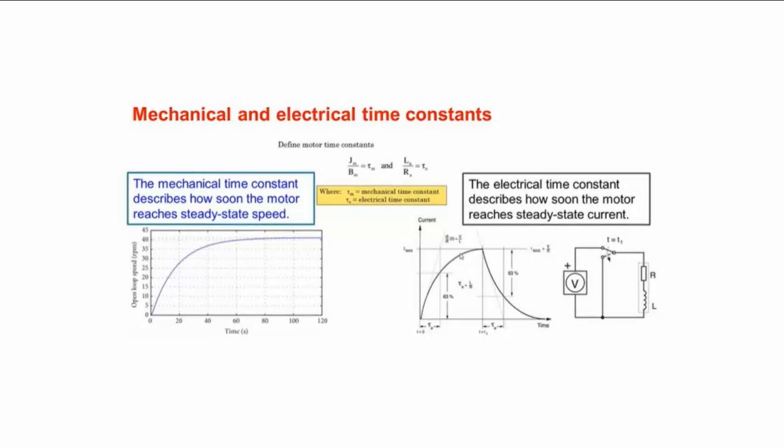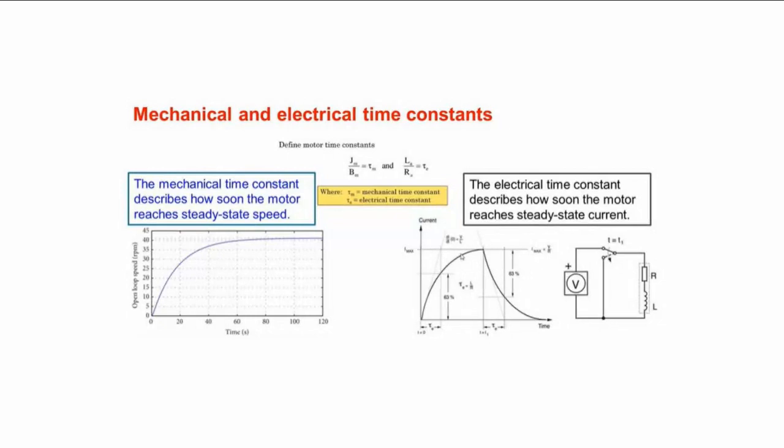Okay, this is tricky. Now, we can either have voltage in and rotation out, or rotation in and voltage out. But every motor is also a generator, I said to you, and the back EMF constant tells us this. It is turning, and it generates a voltage which subtracts from the externally applied voltage over here.